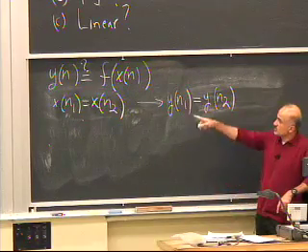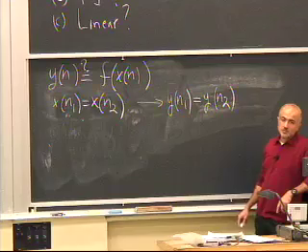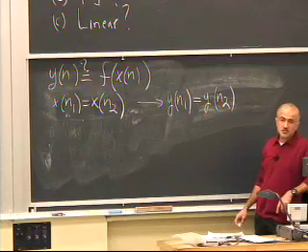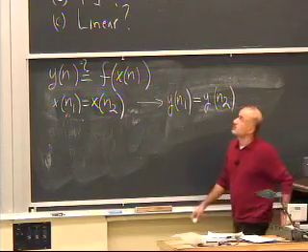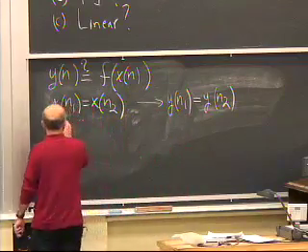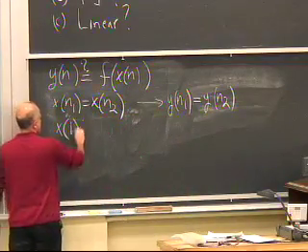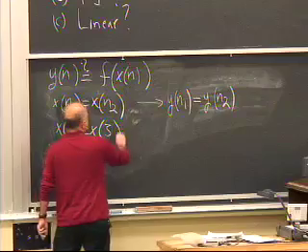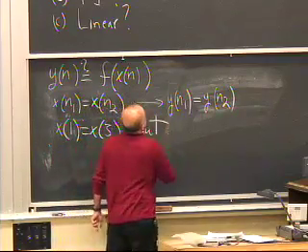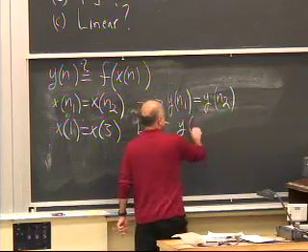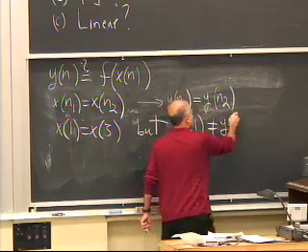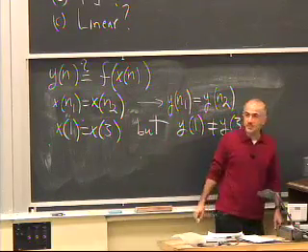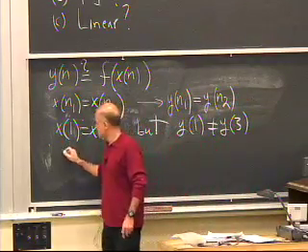So give me two instances in time where the input signal values are equal, but the output signals are not. X of 1 and x of 3. X at 1 is equal to x at 3, but y at 1 is not equal to y at 3. So this system cannot be memoryless.